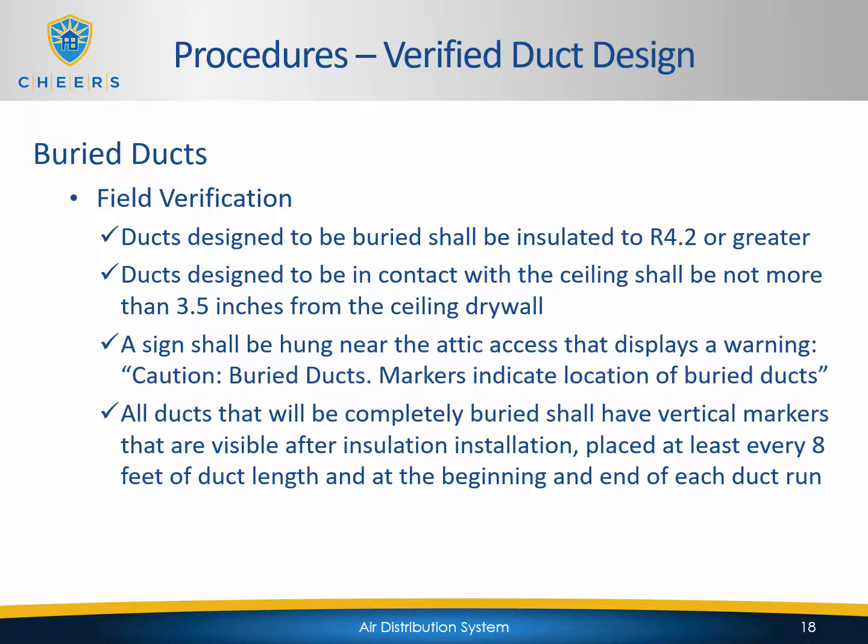So the field verification of the buried ducts credit will require you to do the following items. First, any ducts that are designed to be buried shall be insulated to R4.2 or greater. Oftentimes the prescriptive or compliance side of things will require a value greater than 4.2, but that is the absolute minimum. Any ducts that were designed to be in contact with the ceiling shall be not more than 3.5 inches